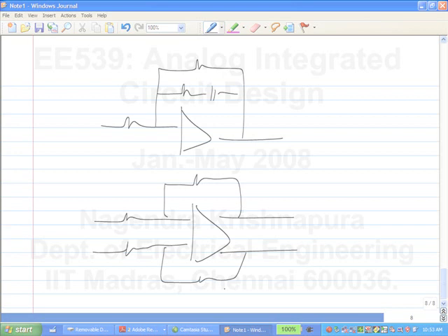No. First of all, you said something about fully differential. The two-stage, whether it's single-ended or fully differential, should behave the same, right? I design, let's say, an input differential pair, certain output stage with a certain Miller compensation capacitance. Now I simply replicate the second stage on the other side and the same Miller compensation cap. I should get the same bandwidth. Now the phase margin will be slightly improved because of the absence of the mirror pole and zero. Okay. Besides that, there should be no change.